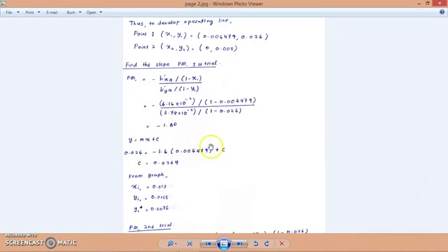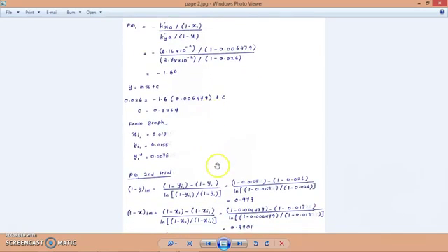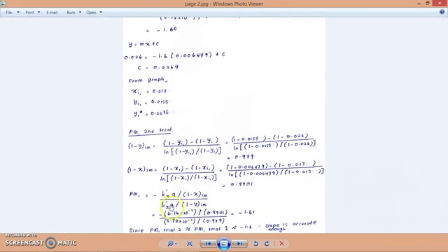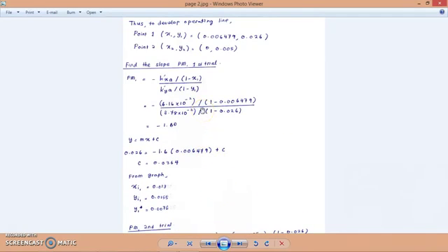In order for us to find the slope, we have to use the equation of slope for a packed absorption column, which is minus k'x a over (1 minus x1) over k'y a over (1 minus y1). The original equation of slope for a packed absorption column is actually this equation, where we have to find the value for 1 minus xim and 1 minus yim, which we don't already have, because we don't have the values for xi1 and yi1. That's why for the first trial we have to use this equation.